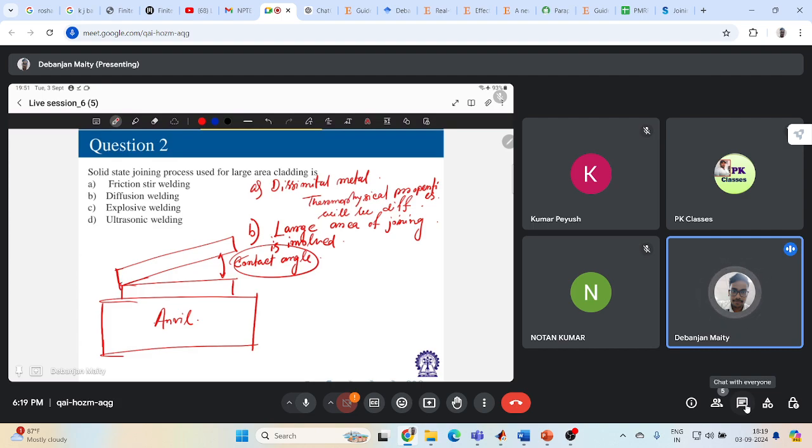Ultimately, this will have some velocity through which it will impact this plate. Let's say this is copper and this is aluminum. So I will provide some impact velocity in the copper. So it will gain some kinetic energy because of this detonation and those things. So it will have some contact angle. So this is a process parameter. And over here, this is the explosive.